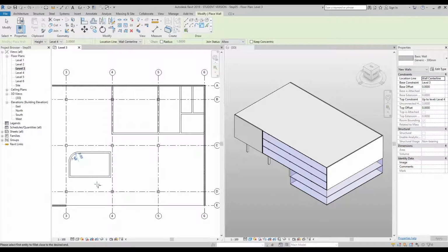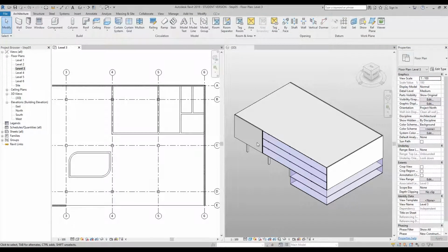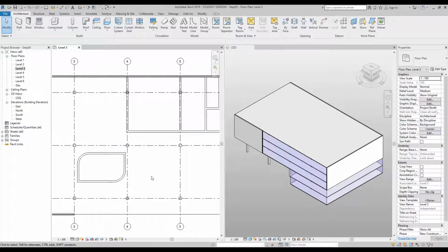I'm now going to do this on the bottom right hand corner, so select the right wall, the south wall, click approximately 3.1 and then change this to 2.0 and then press return. And now I'm going to press escape to finish the command and escape again to go back to our normal user interface. The next thing we're going to do is add some openings to our kitchen.